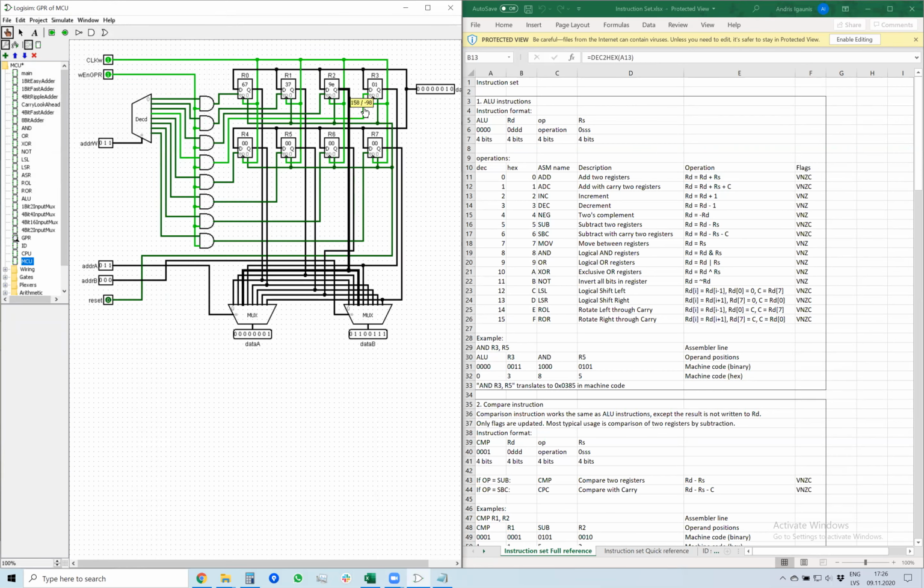I set it this way, so when I click on a wire, the first number it shows is the unsigned number, because most of the time people who program microcontrollers use unsigned numbers. We want to use all 8 bits without sign, because in most cases the counters are positive. Analog to digital converter results are most of the time single-ended positive. So we don't really need signed numbers. We just use all 8 bits as an unsigned number, and we make sure that we never go over 255.